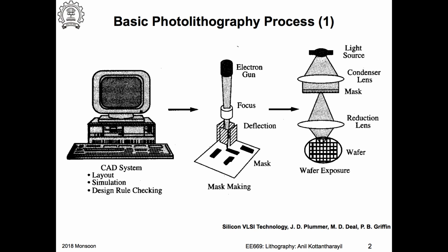So the throughput here is very, very large compared to this, which is a very important consideration in manufacturing. Photolithography systems have very high throughput. Electron beam lithography though is very precise, and you can make extremely small features, because what limits the dimensions of what you finally print on the wafer is determined by the wavelength of whatever you use for excitation.